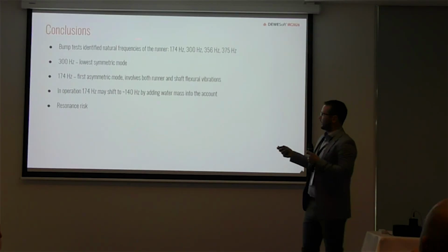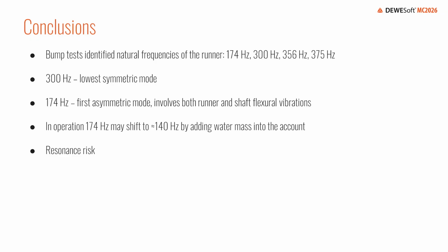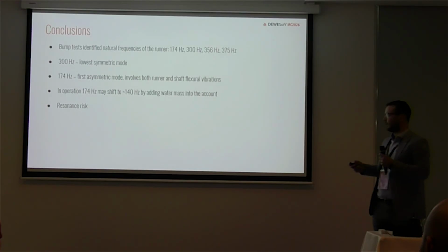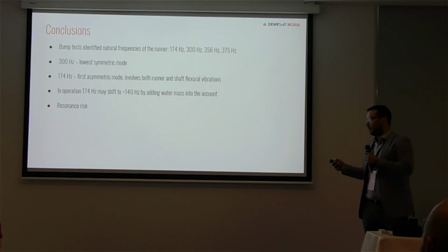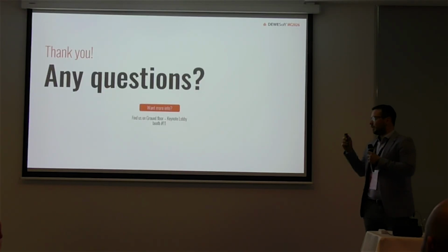Some conclusions: we did the bump test, and the first asymmetric mode is at 174 Hertz, which may shift to 140 by adding water mass into the runner, and there's a possibility of resonance, which probably happened here, and this is it. Thank you.